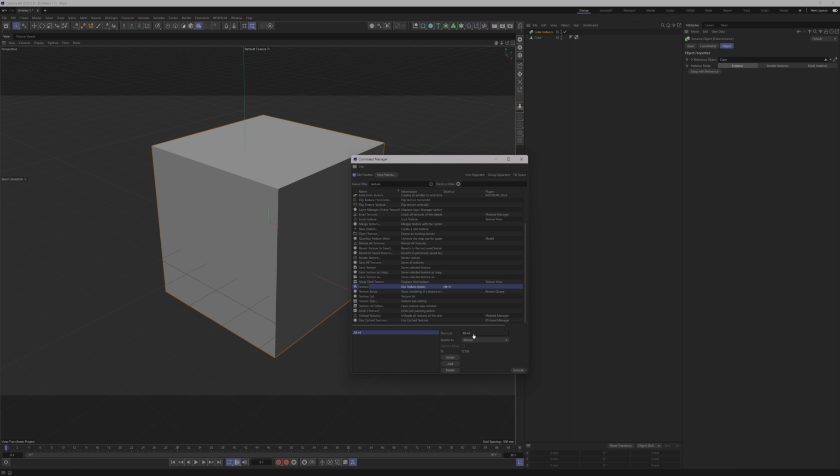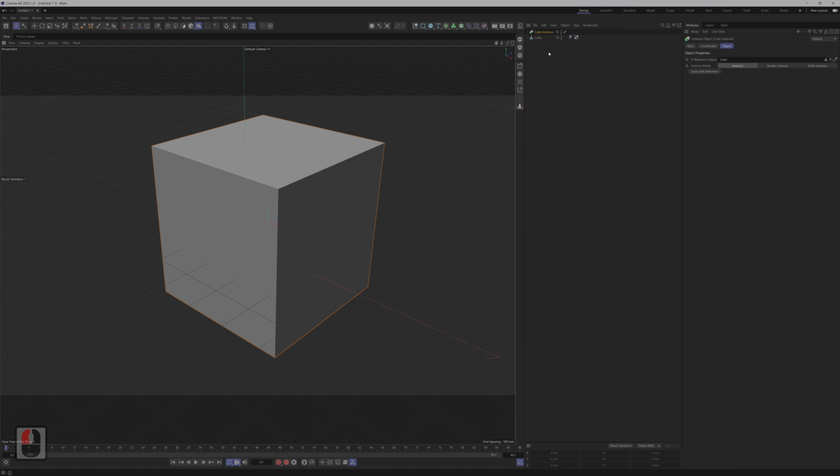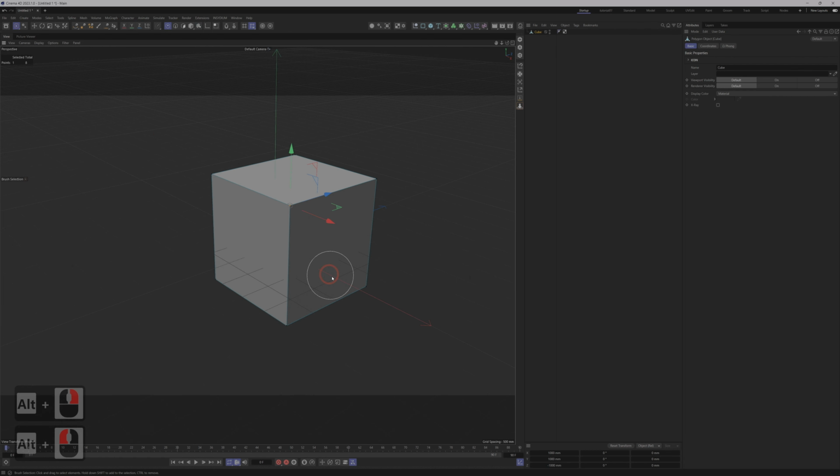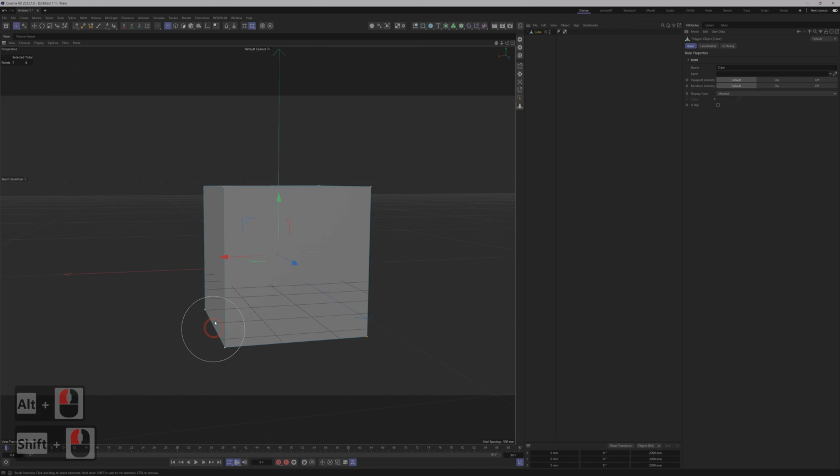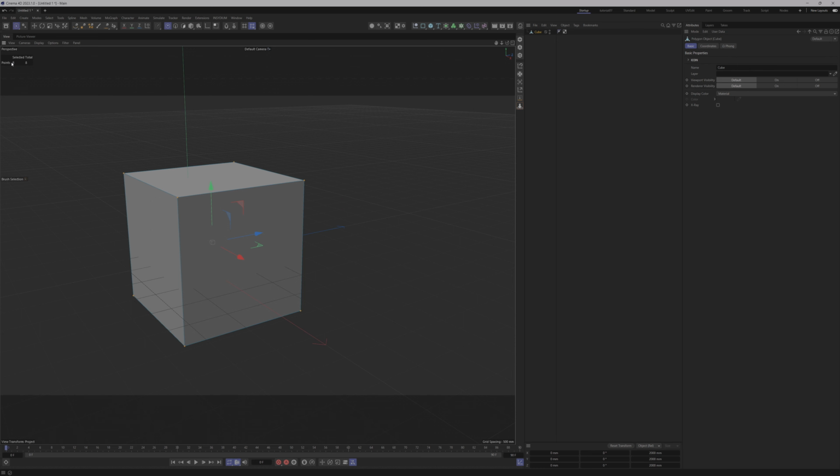Also, one thing I do is visible. Toggle visible only. I put it to Alt tilde. I'll show you what it does right now. So when you have a geometry, the cube should have 8 points, including the back, right? And if you look over here, 8 out of 8.